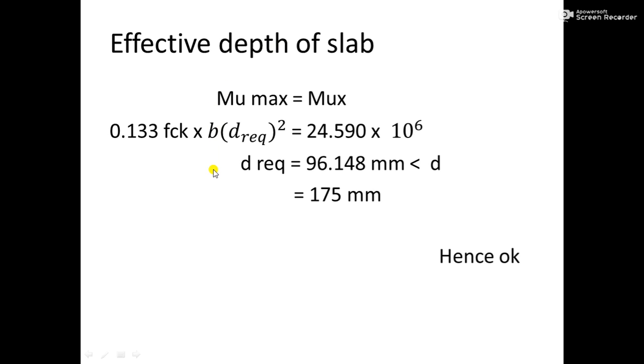So you have to calculate the bending moment along y direction. It is always less than the bending moment along x direction. I have calculated directly the bending moment along x direction, not along y direction. But it is required while calculating the steel area.